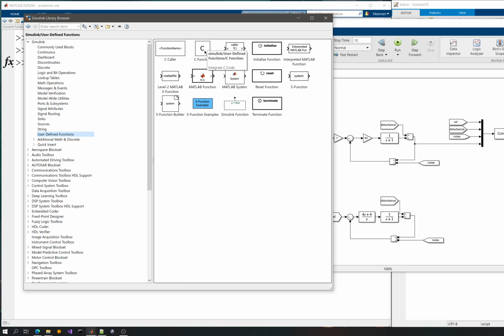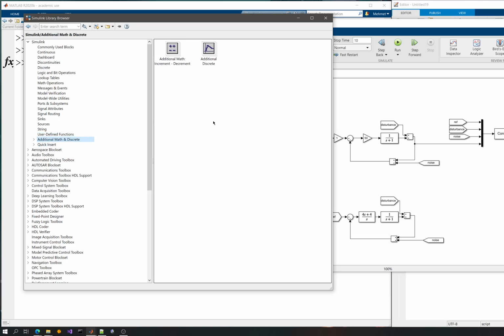functions. Now, this is a nice addition if you think about the slowness of Matlab. Sometimes you have some algorithms in C that are very, let's say, speed dependent. Then you might want to code that part in C and use MATLAB for your simulations, which is very nice. You might want to create, let's say, a basic C function that uses some data coming from a server, and you can implement TCP/IP using a C function. You might want to use that here, so you can extend your model as you wish, basically.